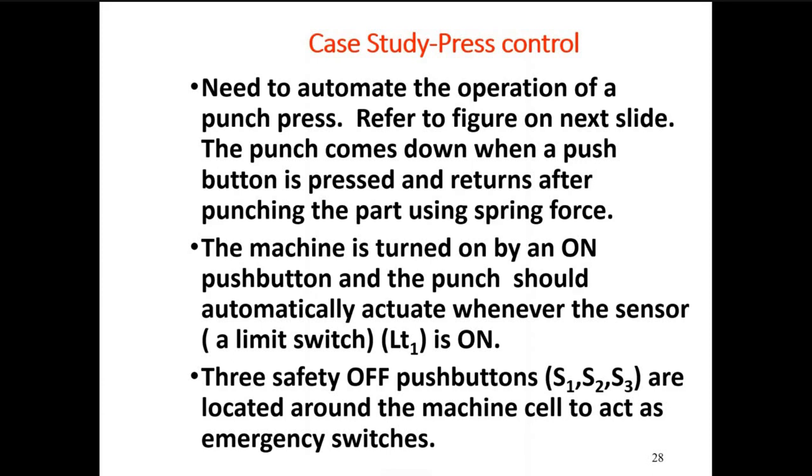I am going to locate two sensors. One to tell me when the piston is home and one when the piston is advanced. So let's assume it is a limit switch or a photo sensor or a magnetic sensor. It could be all kinds. So I'm going to mark them as inputs. They are inputs to the PLC, indicating whether the machine is home or not home.